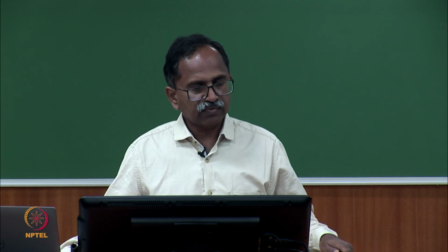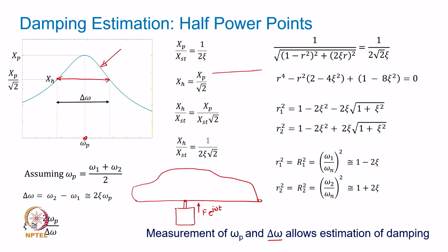So, testing that way is a big problem, but you imagine how simply you excited your simple vibratory system into a free vibration decaying sinusoid response. You could simply put an accelerometer here and generate that response, but then it applies well to simpler and smaller systems. Many times you need to excite it, so people use an impact hammer or a small gentle tap. You can't do that with bigger systems.